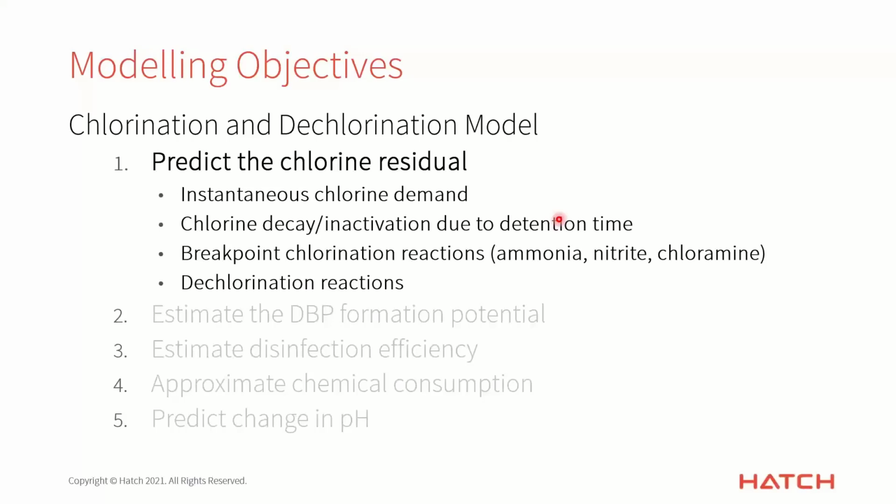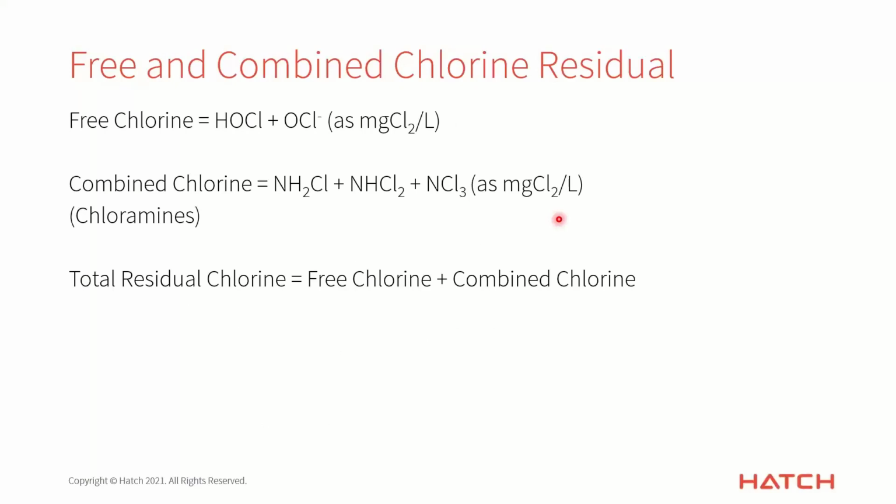The instantaneous chlorine demand, the chlorine decay or inactivation due to detention time, the breakpoint chlorination reactions, and then the dechlorination reactions. So before I get into exactly how we predict a chlorine residual, I want to briefly talk about what the actual chlorine residual is and remind anyone who needs a reminder on chlorine residual and free and combined chlorine.